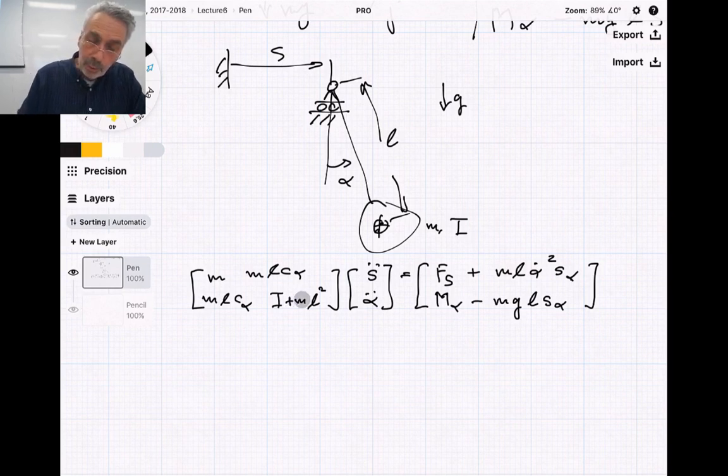The other one, this one, we can also easily identify if it's correct. So that is just about rotation, about swinging. So you keep this constant, and then you have a swinger here with an alpha double dot and a torque, and apparently around this point of rotation. So the torque we feel there is apparently the mass moment of inertia here, which is the mass moment of inertia here plus mass times distance squared. So that's I plus ml squared. Yeah, correct. So these terms are correct.